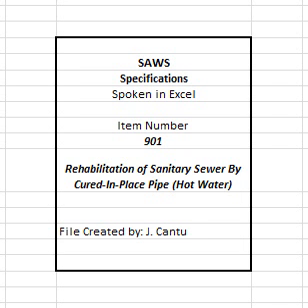5. If a field wet-out procedure will be used for liner impregnation, submit a complete description of the proposed wet-out procedure with detailed information on equipment and material storage locations, resin volumes and/or weights, liner length, start times, finish times, resin injection locations, and any other pertinent data documenting the wet-out procedure. Provide plan indicating procedure for reconnection of laterals and pipe end seals.